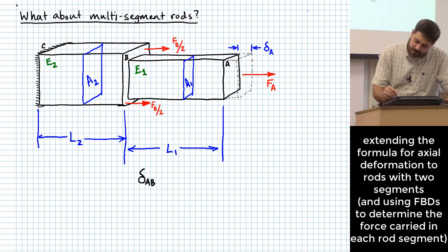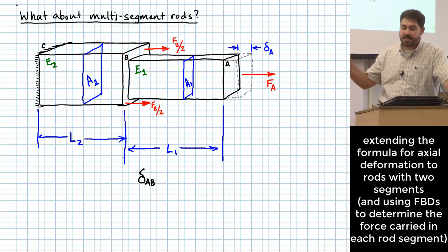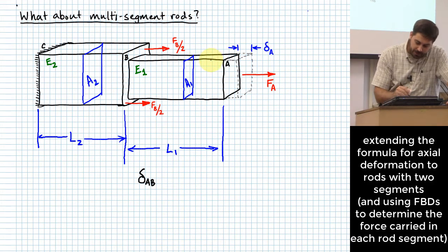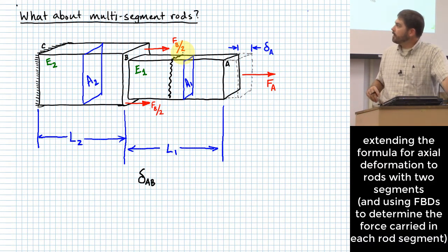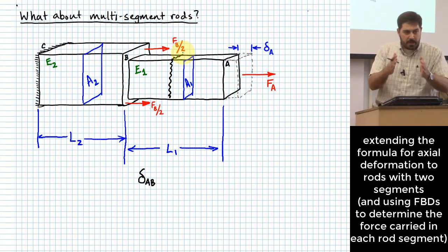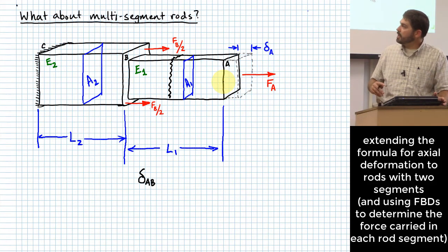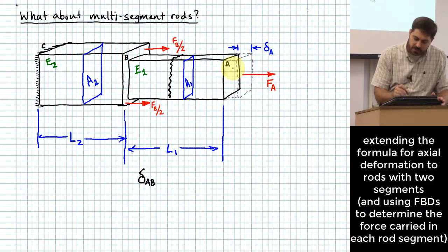I'll tell you what, I'm going to be really persnickety here and say I'm going to assume I don't see anything at all in terms of what that should be holding. Here's what I should do if I need to figure it out. You make a cut in that member. You say, I'm going to chop that member not at either of the ends, but somewhere in the middle. If there are no changes in any of the parameters happening from A to B, then chop somewhere in between and do a free body diagram of just one side. Something like this.